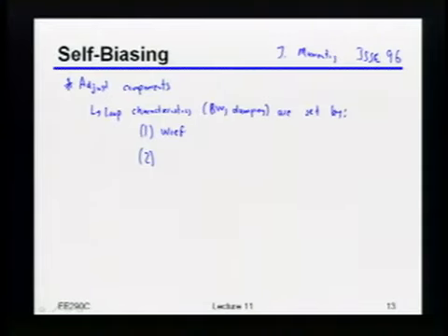Yeah, you want to make things be set by ratios of identical components, right? So in other words, you want this to be set by ratios of, for example, capacitors, resistors, etc. The exact physical components you use to ratio is not so critical. We'll see that typically it will end up being ratios of capacitors.